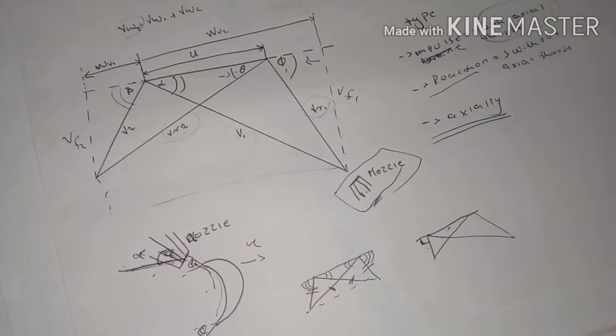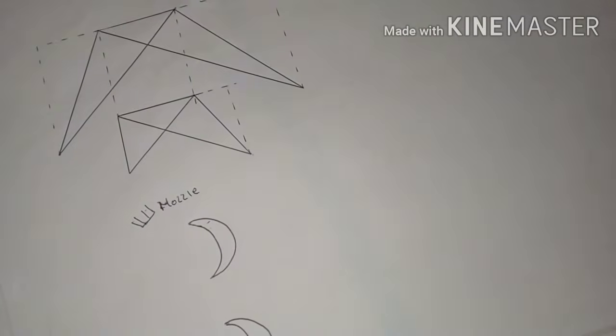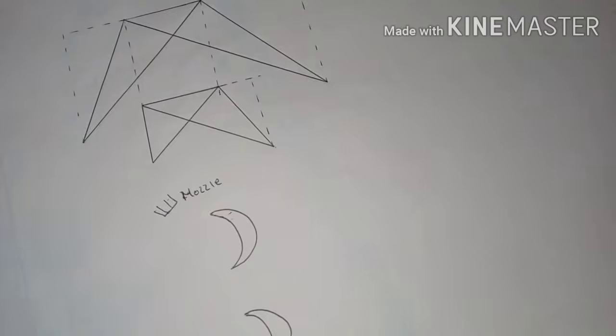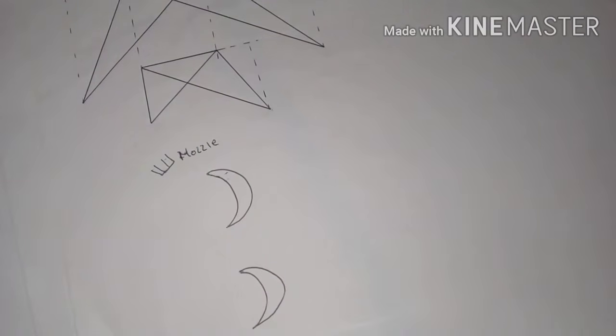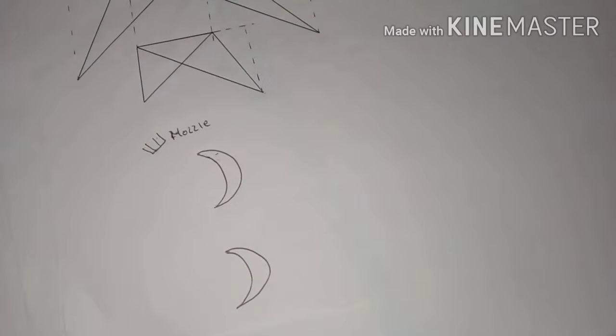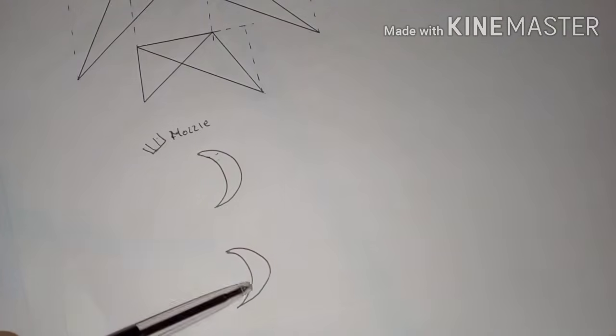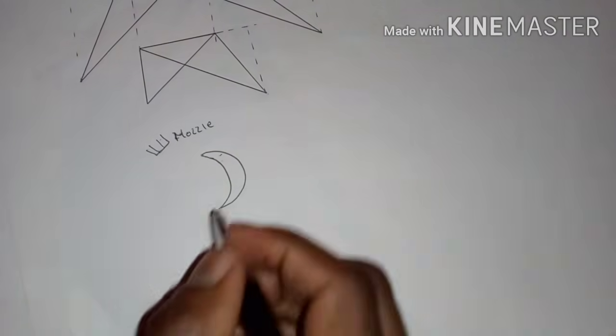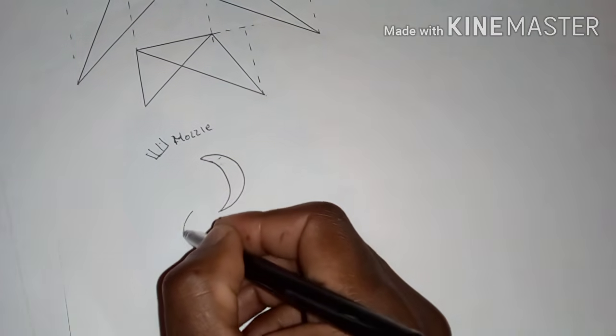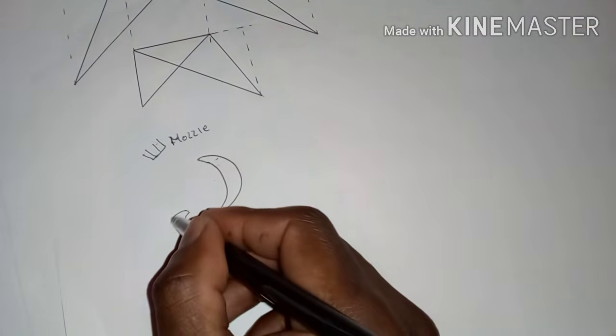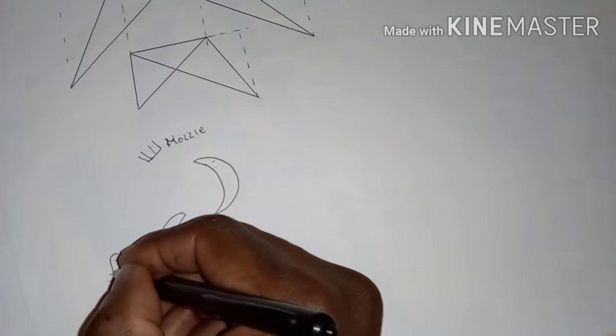So even now, nothing is changing. We are just advancing from what we know. Now, instead of dealing with one blade, we will be dealing with two blades, giving us a two-stage velocity diagram. We want the steam to glide through this blade and then also through this blade. What we need to introduce is what we call a fixed blade. This one is fixed.